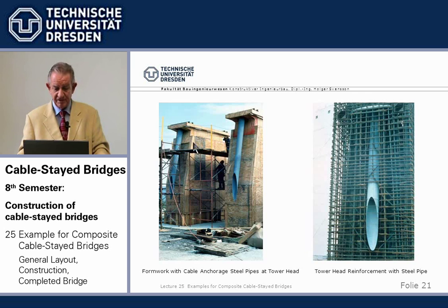These are the inner forms from timber, and here are the first very steep steel pipes. And then, of course, around that is an outer form and cast into concrete. In the next step, the reinforcement is placed here around the steel pipe. You can see it here. And here you just see one of the loop tendons, I told you, which tie together.